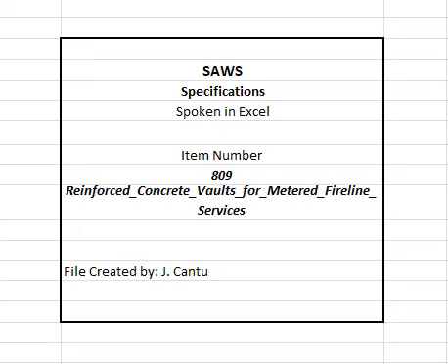D. Submit manufacturer's mill certificates for reinforcing steel. Provide specimens for testing when required by project manager. E. Submit certification from concrete supplier that materials and equipment used to produce and deliver concrete comply with this specification.